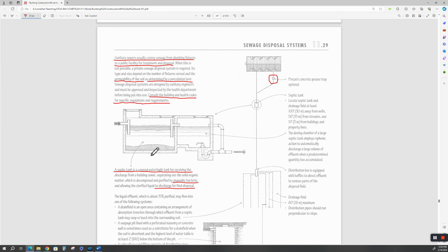The 69th Street sludge dewatering facility or furnaces, we used 30,000 RPM centrifuges to dewater that sludge, so it was like mud. And then that was conveyed into furnaces, and that sludge was dewatered, cooked. All the pathogens were killed out of it, and into a powder. It smelled like pig manure, and pneumatically conveyed to storage silos. And then from the storage silos, we transported that pneumatically to either rail cars, and then we had a barge loading facility where we'd fill up barges full of dried sewage sludge, and they'd take it off and try to sell it as fertilizer.